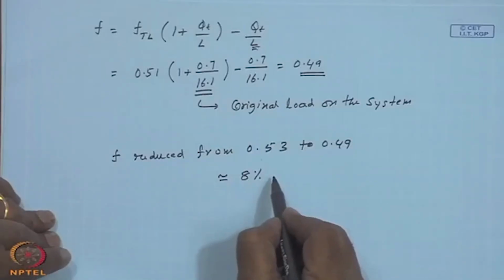Whether the guess temperature is correct or not is found out by obtaining the average utilizability, which corresponds to some average X c bar, which should correspond to an average inlet temperature to the collector. The suggested possibilities being T minimum equal to 60 or whatever, and this Ti bar, we take the average, and if this average is close to the guess that we made in the beginning, then we will stop the iteration. Otherwise, you take the new value that is obtained and go through the procedure again. So, this is how the tank losses can be taken care of.